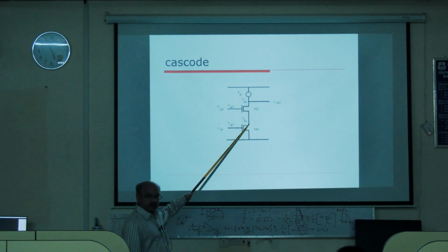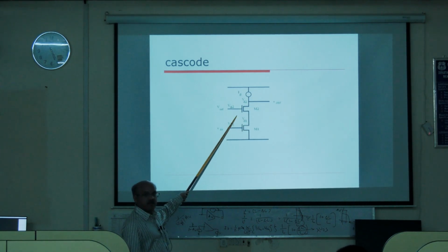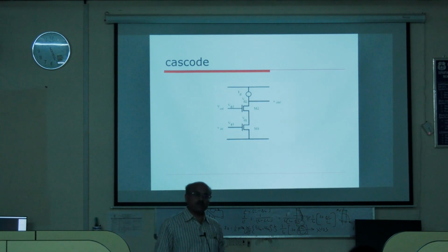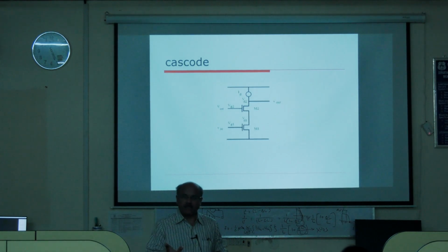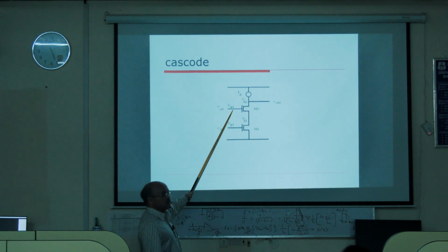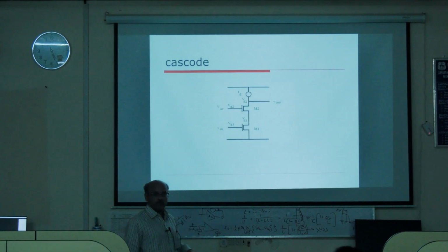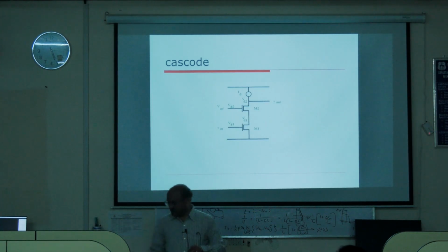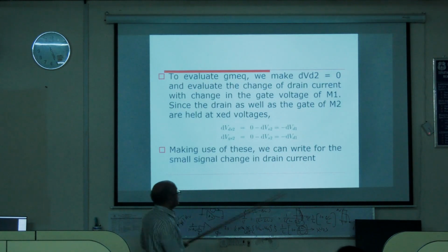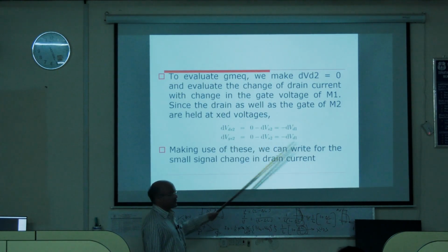You are right. It is the DC voltage. It is not a difference, it is a DC voltage. Therefore, signal I am not applying there. Therefore, delta change is 0. There won't be any change there. Am I right or not? So dVg2, or small vg2, is 0. All the time it is 0. Therefore, this is 0 minus dVs2. dVs2 is again dVd1.